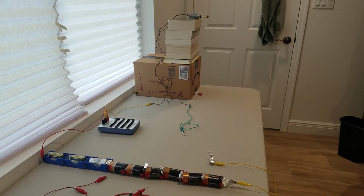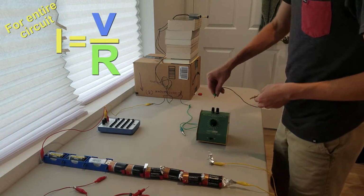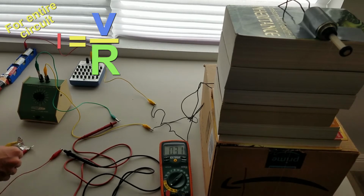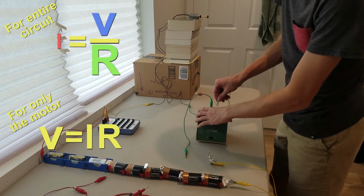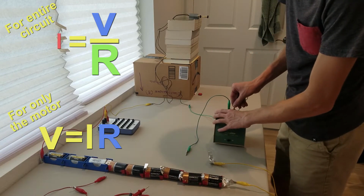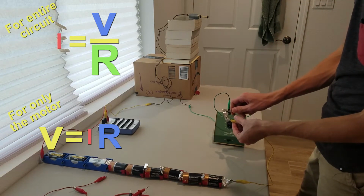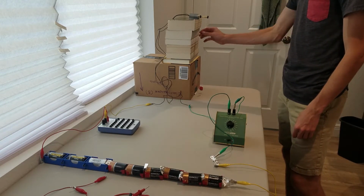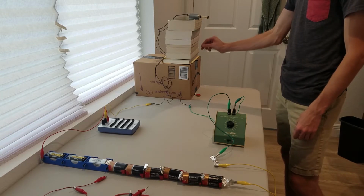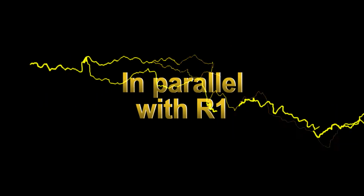When R2 is placed in series with the battery, R1, and the motor, the total resistance of the whole circuit increases, therefore decreasing the current of the circuit, which is the same in all parts of the circuit since everything's in series. If we look at just the motor using Ohm's law again, the resistance of the motor is constant while the current through it decreases with the introduction of R2. This means the voltage across the motor will also decrease, which in turn increases the time interval. In the demonstration, the voltage became so low across the motor that it was unable to lift the mass.